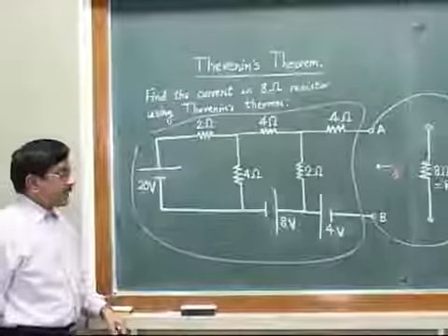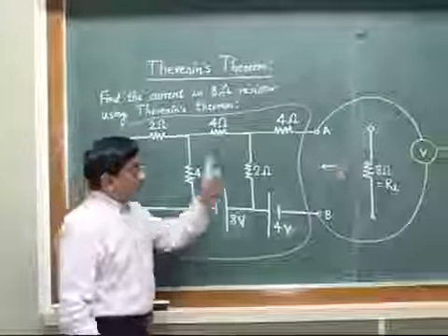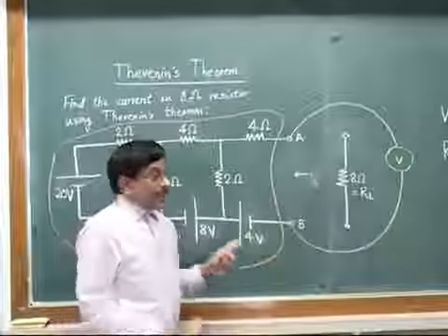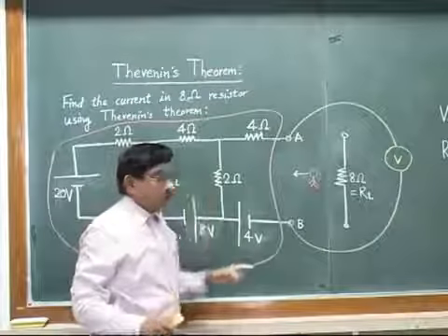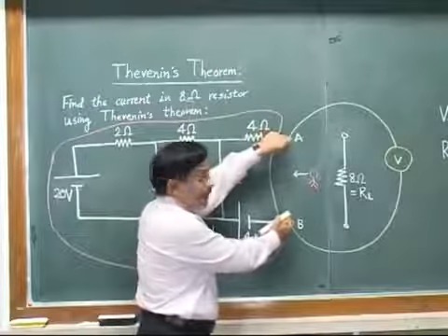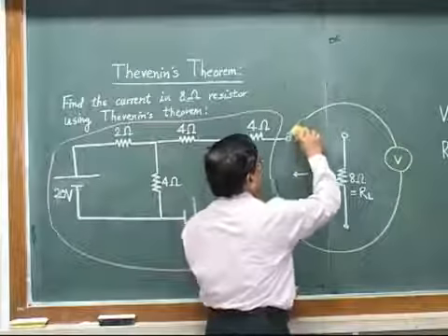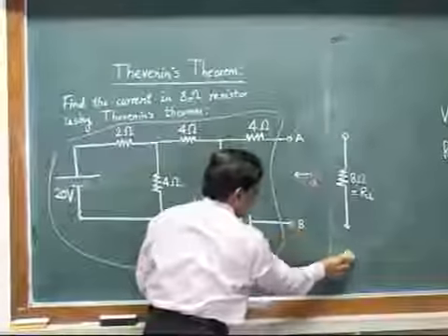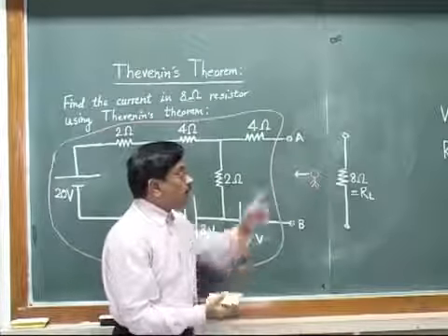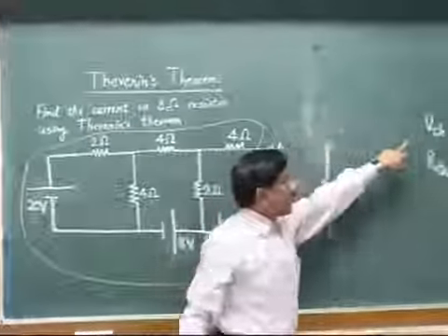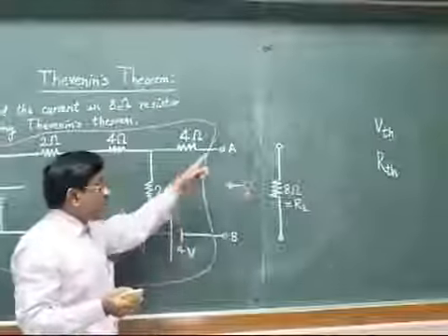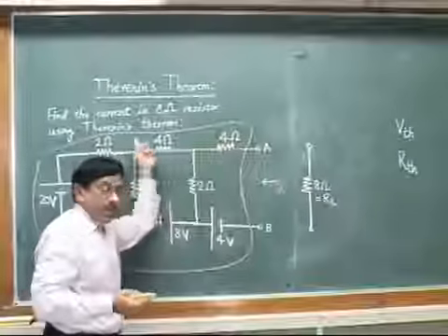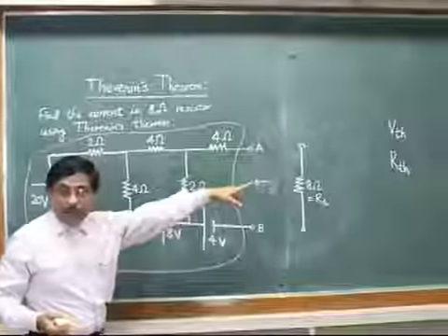So what is the idea given by Thevenin is that when you remove the load resistance, then you get 2 open ports like A and B. Then the entire circuit in the red box will give some open circuit voltage or potential difference between points A and B. I just remove the voltmeter now because I had shown it just to explain the idea of open circuit voltage. So that single value of voltage across A and B is the VTH now, and that single value of resistance, which is equivalent to the entire passive network inside the box, is now RTH.